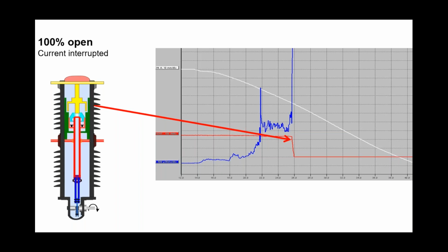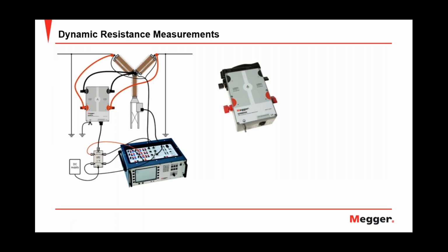As disadvantages, for the circuit breakers which have built-in CTs, usually dead tank circuit breakers, the current flowing for this test will end up magnetizing the CT cores, and that can lead to further issues with the way the protection will measure the currents after the re-energizing, and that can lead to false trips of the circuit. So if you use the dynamic resistance measurement method for contact time, you have to make sure you demagnetize the CTs which were in the circuit.